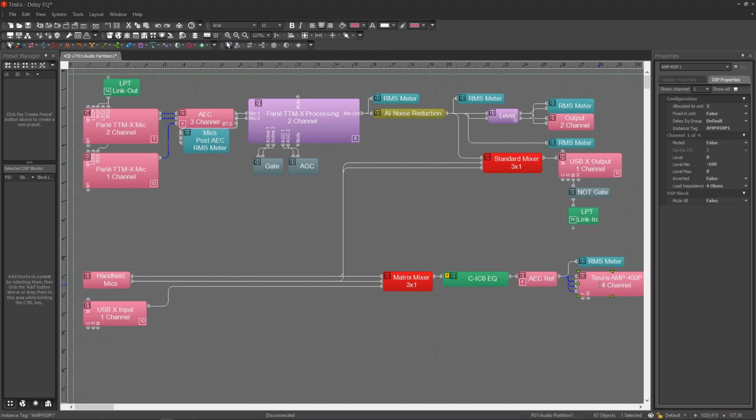But when we're getting them to the local loudspeakers, if we have 50 odd milliseconds, 70 milliseconds of latency there, the person that's going to be speaking in the room is going to hear that delay. And when you hear a delay of yourself coming back, it's off-putting. So we can do something about this.